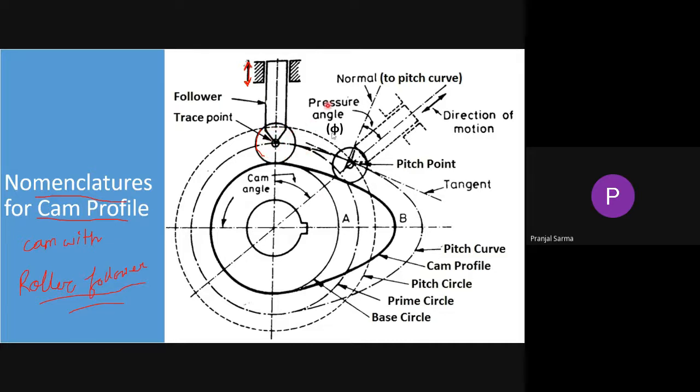Okay, so now, what is this? Can anyone tell me what this portion is that we are showing? This is the portion where the shaft will fit here, and this portion is the keyway, where the shaft will be keyed to that particular cam, so that when the shaft rotates, which ultimately becomes the axis of rotation of the cam, the cam will rotate along with that shaft.